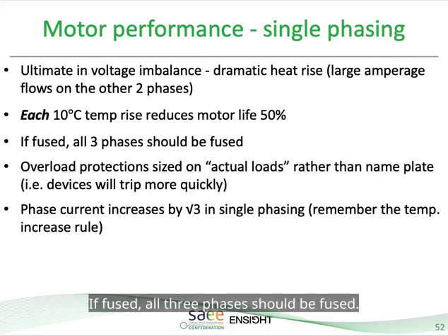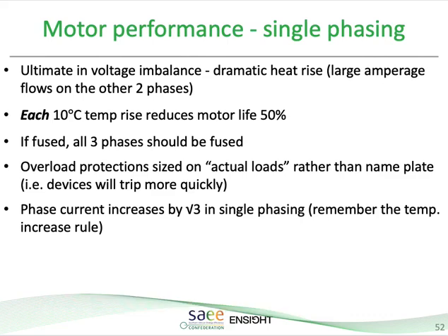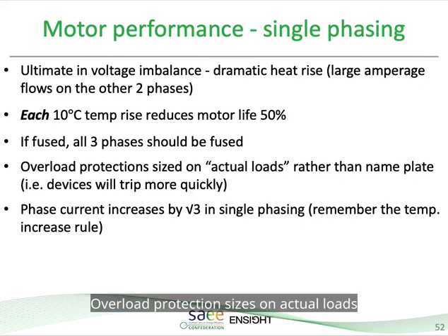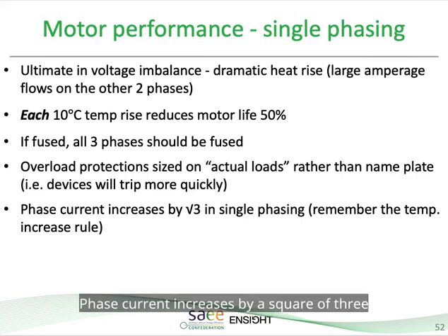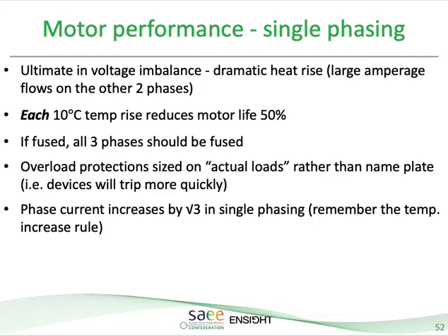If fused, all three phases should be fused. Overload protection should be sized on actual loads rather than the nameplate loads. Phase current increases by the square root of 3 in single phasing. Remember the temperature increase rule.